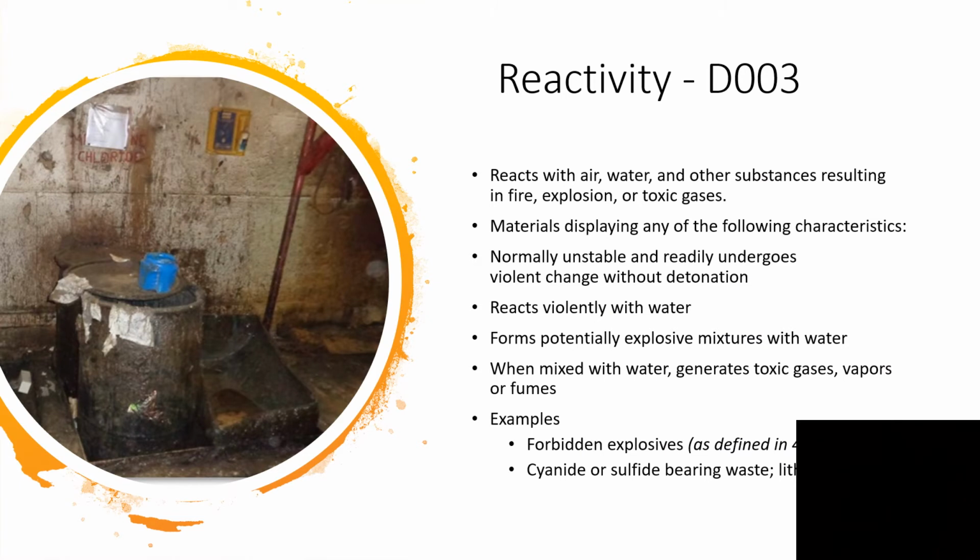For reactivity, this means that it reacts with air, water, or other substances, resulting in fire, explosion, or toxic gases. Materials displaying the following characteristics can be categorized as reactive. They are normally unstable and readily undergo violent changes without detonation.